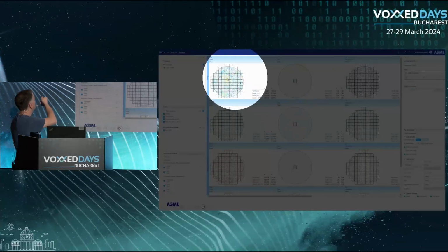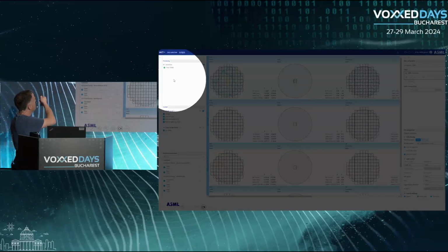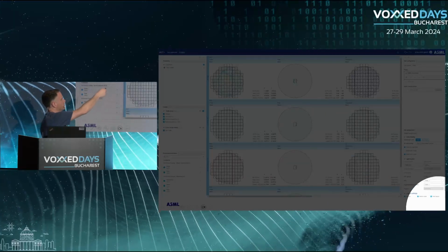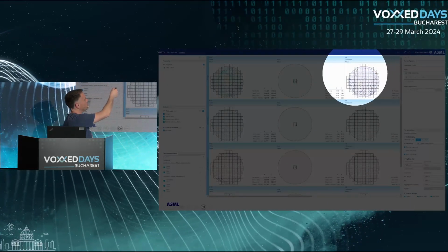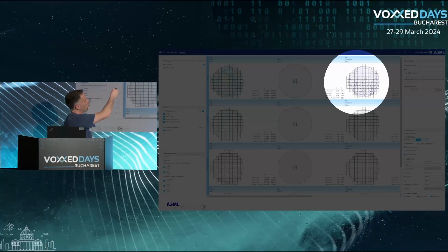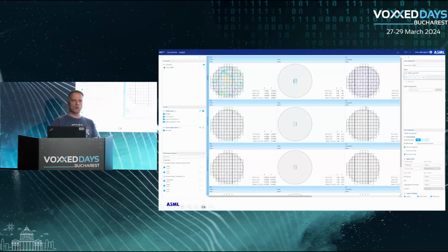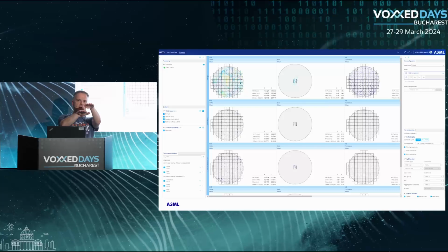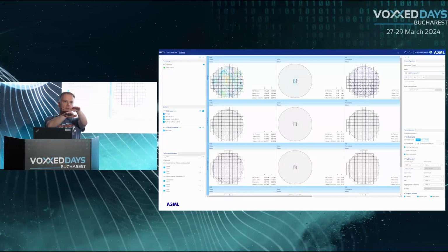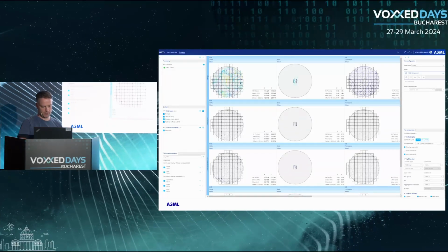So for example, here at the top, we see that the TDBB was executed, and that's actually one of the algorithms in the processing plugin. And that resulted in, for example, this. It's called CE, as you can see at the top. It's correctable errors. And what we see is that all arrows point in the same direction, which basically means, for example, if you have 2 layers on top of each other, they are a bit wrongly aligned. So in the next step, maybe we can do it a little bit different and print it like this. That's correctable. We know how we can fix it.